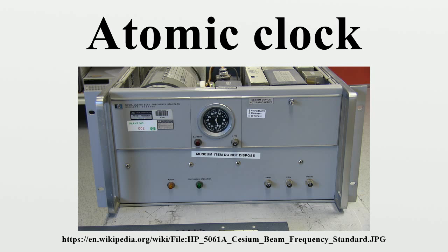A typical rubidium gas cell uses a rubidium lamp heated to 108 to 110 degrees Celsius, and an RF field to excite it to produce light, where the D1 and D2 lines are the significant wavelengths. An 85Rb cell filters out the D1 line so that only the D2 line pumps the 87Rb gas cell in the RF cavity.